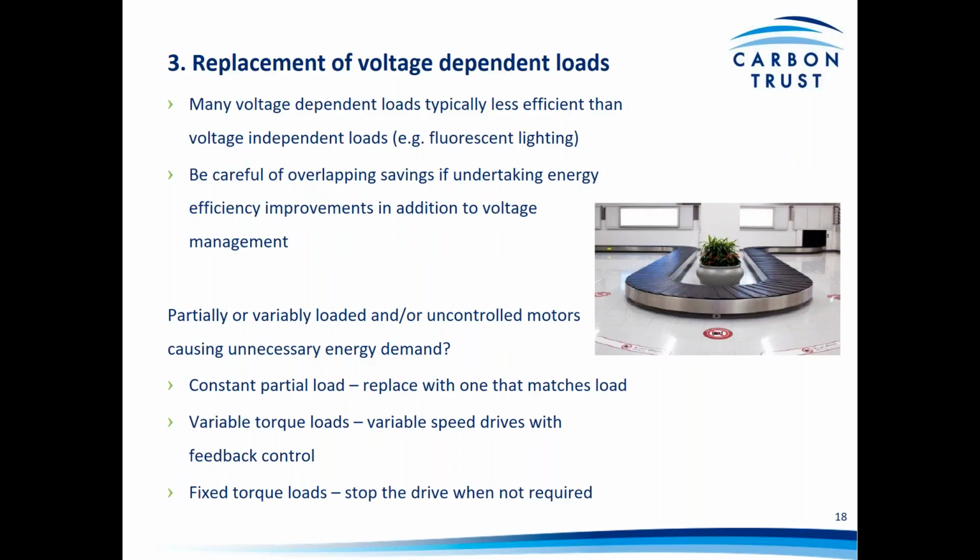One thing to flag here is just to be careful not to overlap any savings. So if in the example I just gave you, we're looking at installing voltage management equipment or techniques at the same time as, say, going through a program of replacing all fluorescent lighting with LEDs, it's just worth making sure that you're not overlapping any savings that could be achieved by both of those measures, bearing in mind that voltage management would have no impact on the efficiency of the LED lighting.